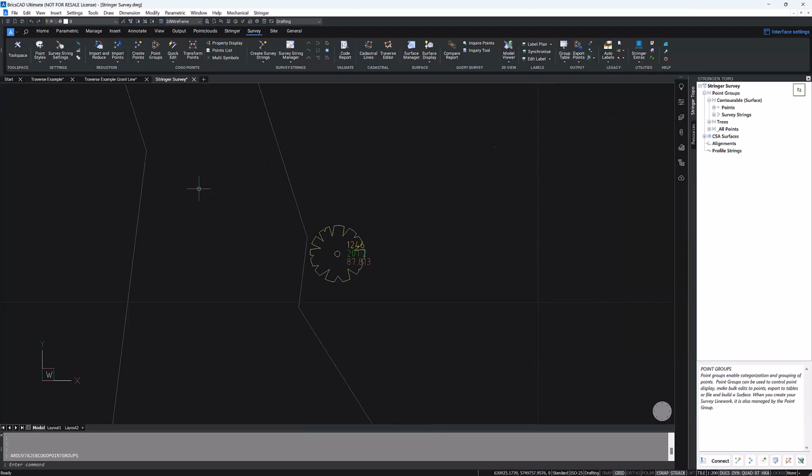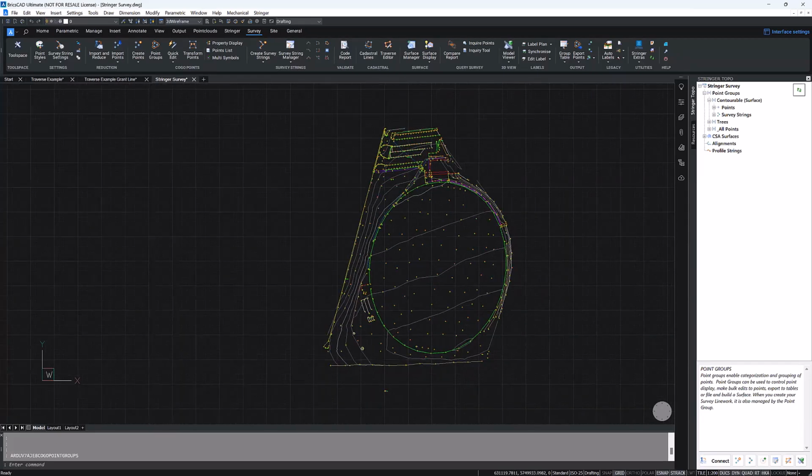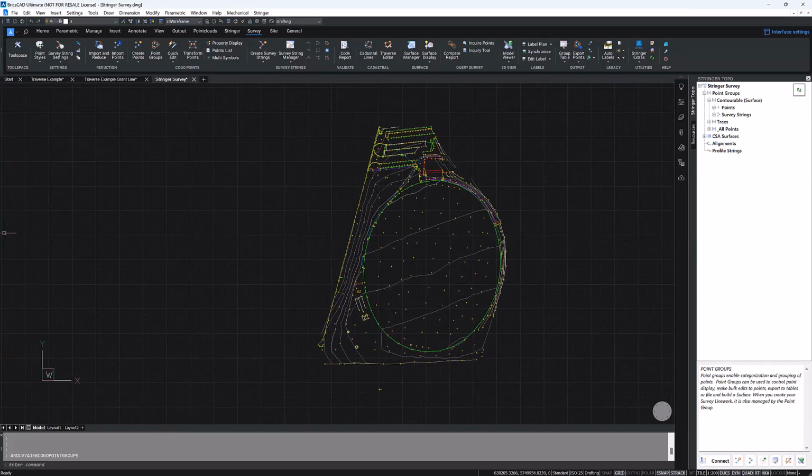But if I make any changes to that database, I can also come back up here, and sync links is the option that's automatically selected, ready for me to work with. So I'm able to sync that information as needed anytime I make an update to the Excel document. It's a very powerful tool, allows you to very quickly add information to your drawing as needed. And I hope I'm really getting that across.